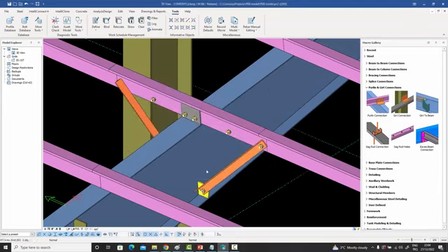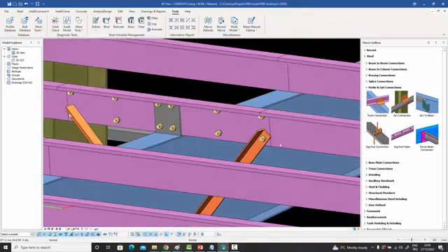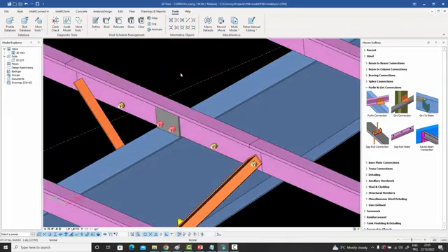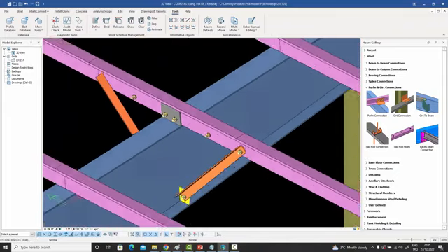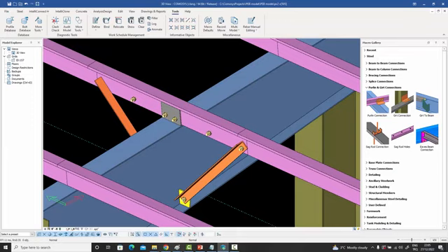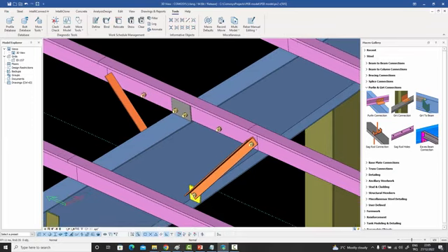And if I do that, immediately those struts are created on either side of the connection. And now, since the bolt IDs are different, this is a single bolt because it's going through the strut as well, and this is a separate bolt. These two are one ID, and these four are one ID because they're going through the plate as well as the other one. So this is a very handy way of creating this new Z-type purlin, overlapped purlin connection, which we have now added to COMOSYS